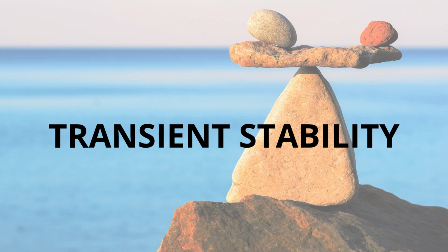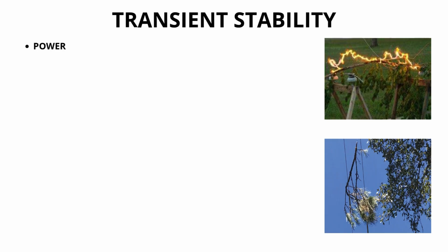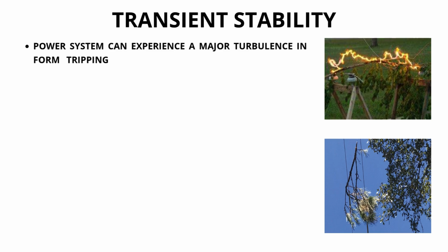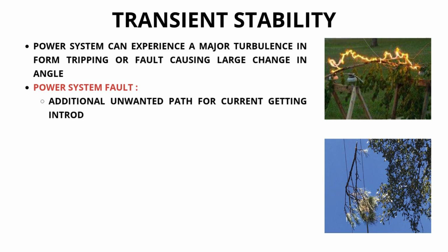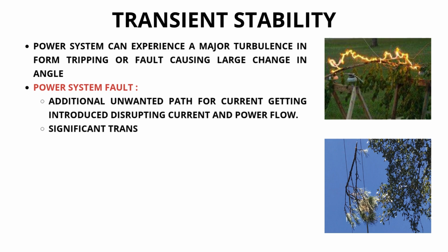All right, let's shift gears to transient stability. This is for the major turbulence, the big hits like faults. Yes, transient stability. This is about whether the system can stay synchronized after a large, sudden disturbance. A short circuit, a fault, is the classic example. How does a fault cause this kind of instability? Well, a severe fault, as the material explains, dramatically changes the grid's impedance. It can essentially block or severely limit the generator's ability to send its power out onto the grid.